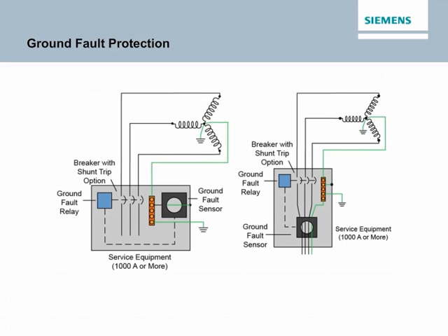One way a ground fault protector works is to install a sensor around the insulated neutral bonding jumper. When an unbalanced current from line to ground fault occurs, current will flow in the bonding jumper. When the current reaches the setting of the ground fault sensor, the shunt trip opens the circuit breaker, removing the load from the line.